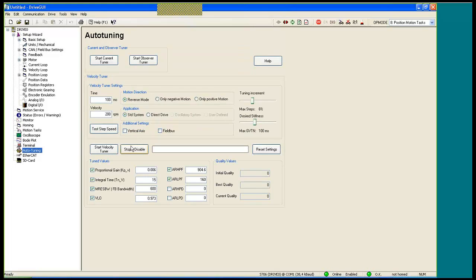Okay. We do have an auto-tune screen that allows you to make some select choices here on how to perform the tuning. It will automatically sample the load, move the load, and appropriately set up the velocity loop proportional integral. It sets the feedback filters. The velocity loop observer is being set automatically. We have 4 filters that can be adjusted automatically. We will be going over this next week in the 3rd WebEx. So just a brief mention on it.